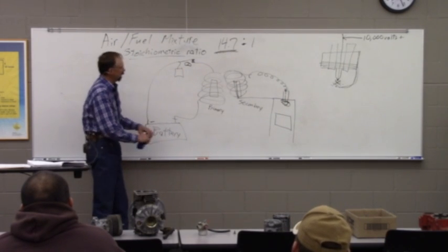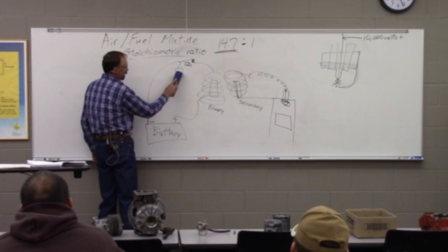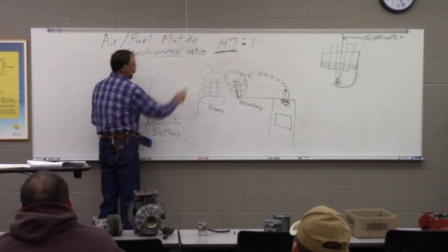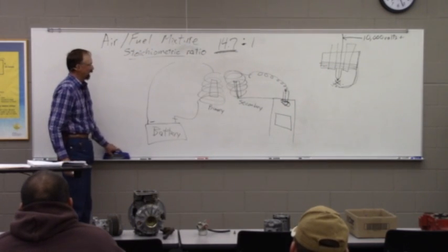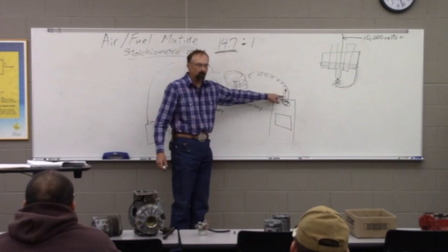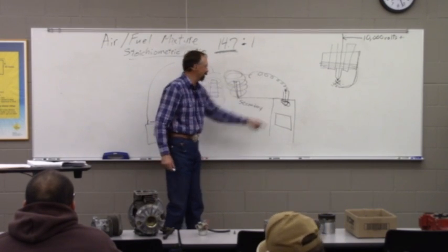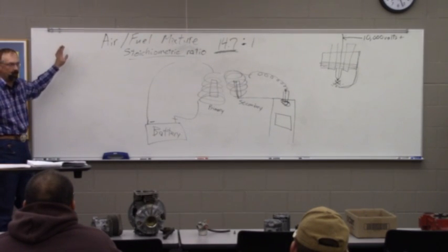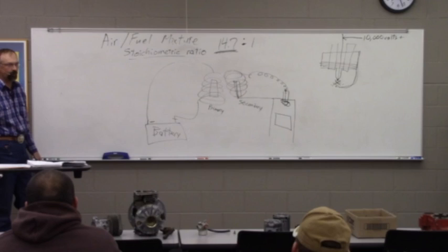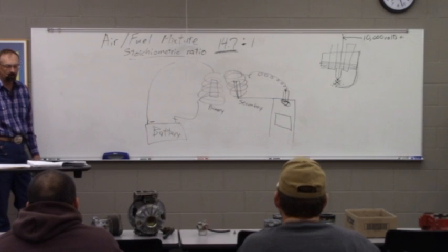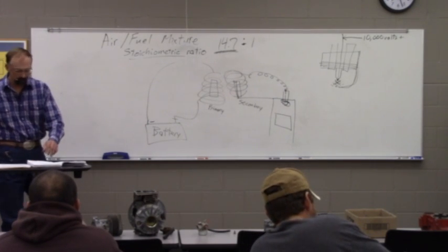So on our more modern vehicles, what we're doing is instead of these mechanical components, we're actually connecting these wires to the computer, and we're letting the computer fire this coil and send spark here when it needs to, and it's calculating that off of that whole list of sensors we were talking about earlier. The majority of those same sensors that are being used to figure fuel mixture, we're also using to figure out exactly when we want that spark to initiate our combustion.